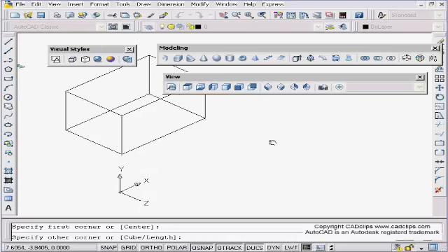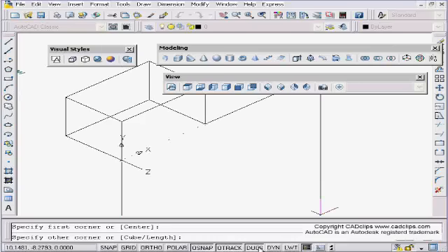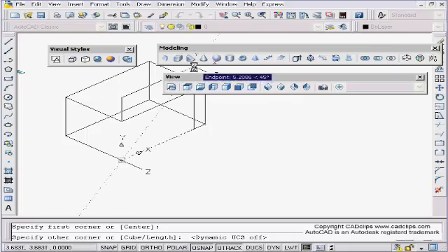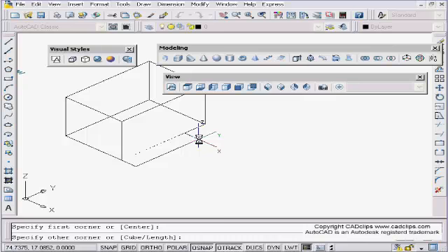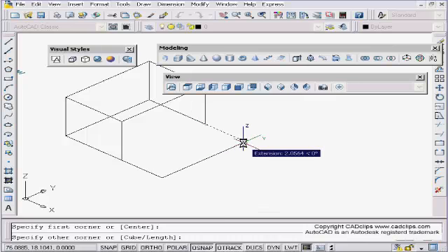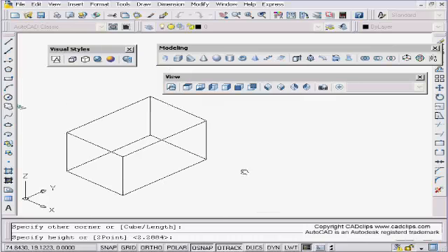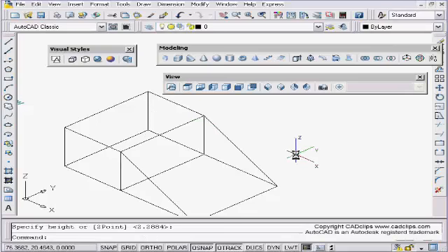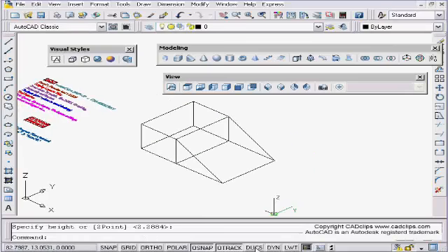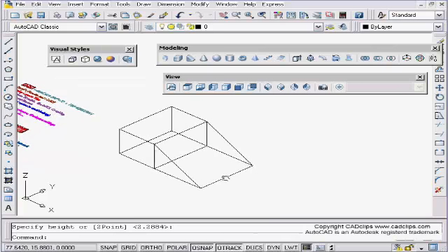I'm going to place, oh, now my UCS. I don't need my DUCS for this one. Wedge from here. Notice it started to draw up the side of that wall. Click, and now I can go pick that endpoint. Okay, I had to turn my DUCS off because the purpose of DUCS is that I can do this.